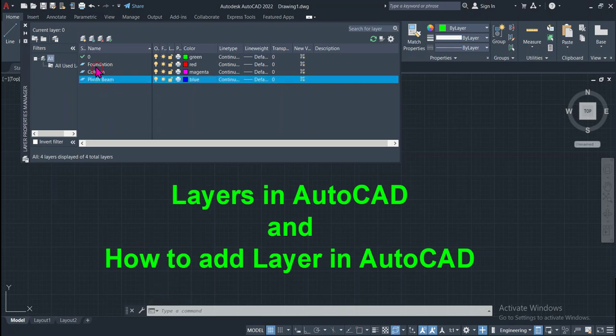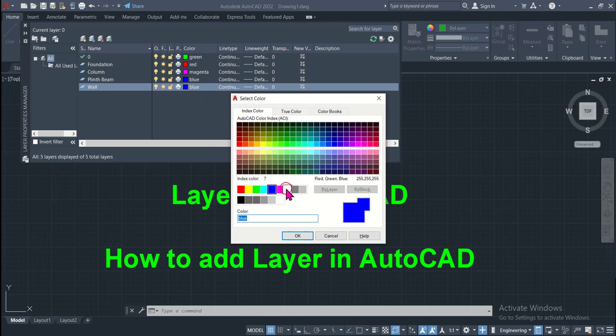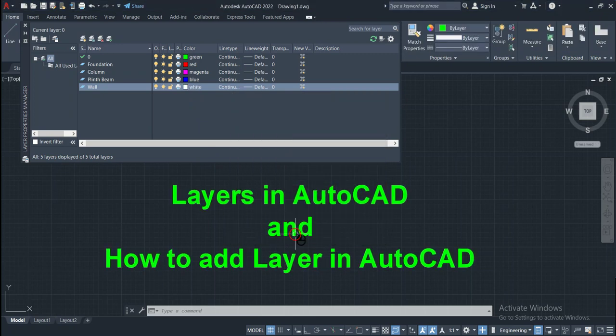Now if we want to add another layer, we click from here and name it. You can give any name to the layer as per your desire. We will name it walls, and we want to assign it a white color. So white color has now been assigned to the layer that we just added, the walls.